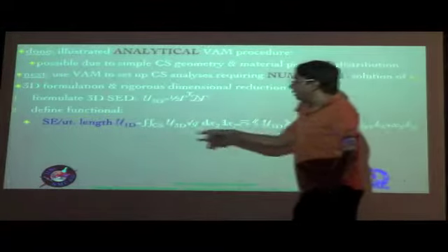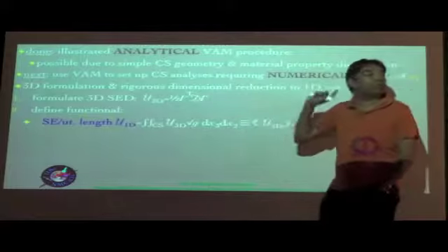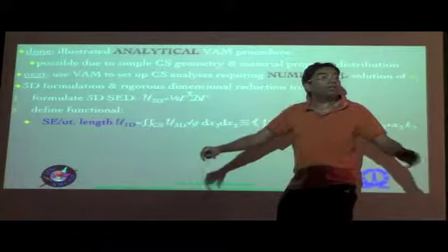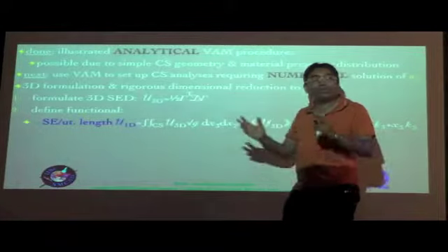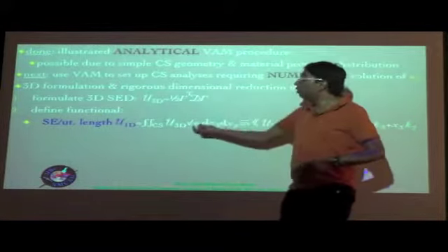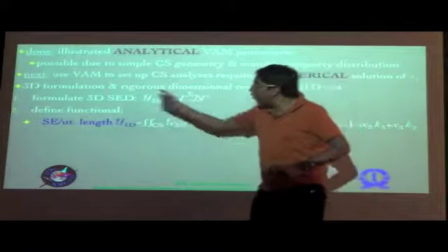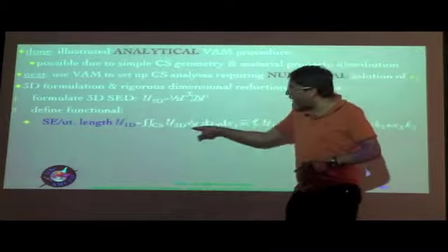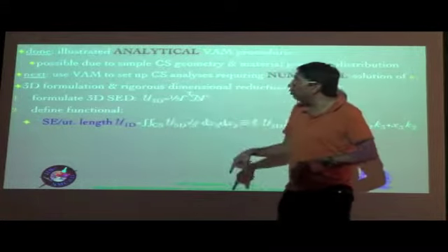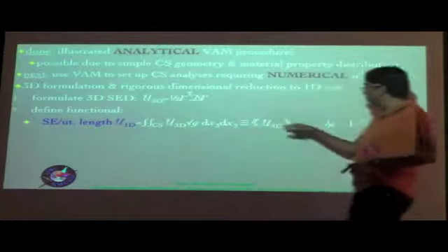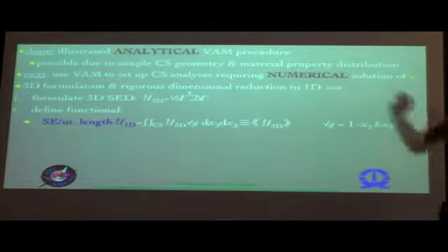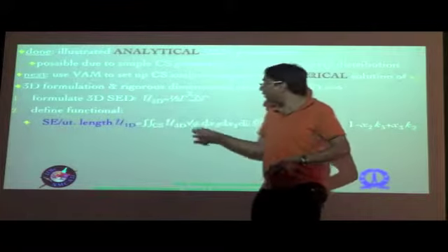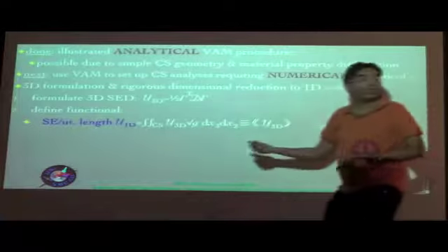Now that is in turn an integral over the cross section, and we also saw in one of the earlier classes the need for having a square root of G, because we are considering initially curved geometry over here, and therefore the volume element would have contributed this root G. Your U would be a volume integral with respect to dx1, dx2, dx3 and root G, then you would have the U3D, but because of the fact that root G depends on x2 and x3, this has to be brought into the integral over the cross section itself because of the dependence on x2 and x3, which are cross-sectional coordinates.